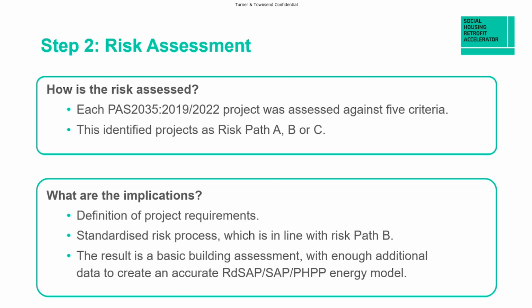And then also it helps you understand the basic building assessment and how you can use the information to help you model performance and outcomes that you can achieve from the different approaches you use. We use mostly the use of RDSAP as retrofit assessors. That's normally what they will use when they go around and assess things. That can be converted into a SAP model, which is a little bit more detailed. And you could also use PHPP if you really wanted to achieve good quality outcomes and really low heat demand.